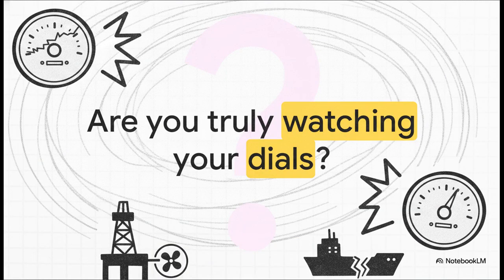But here is the critical operational reality, the thing that should keep you up at night. If a major fault or a massive sudden load swing yanks that load angle past 90 degrees, your magnetic spring just snaps. You suffer a total, catastrophic loss of synchronism, risking severe damage to the prime mover and a complete blackout of your offshore platform. Understanding all of this leaves us with one incredibly important question for your everyday offshore operations. Are you truly watching your dials?